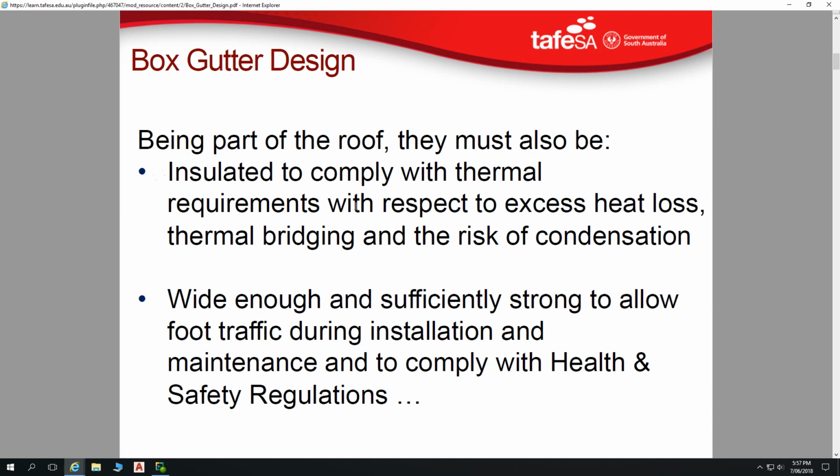Being part of the roof, they must also be insulated to comply with thermal requirements with respect to excess heat loss, thermal bridging, and the risk of condensation. So there has to be accommodation under there for insulation as well. And I'm pretty sure if you look at the box gutters here, on the underside of these box gutters, they're all insulated at the base as well. But probably, as Kane, you would maybe see on sites, it doesn't always happen. Don't know if you. Yeah, well, yeah.